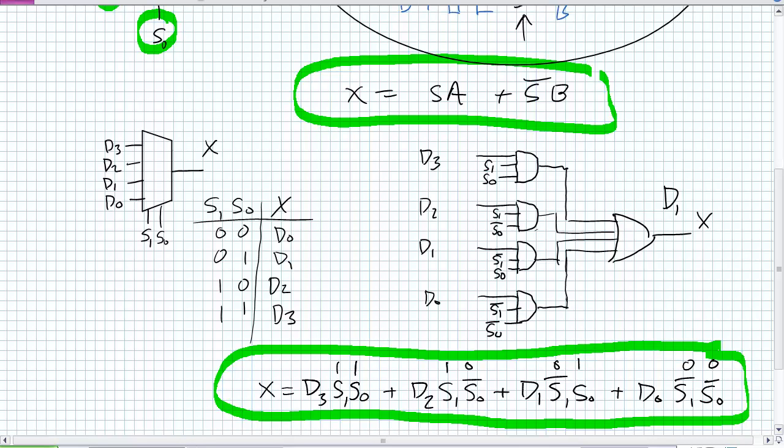Go to an 8-to-1, go to a 16-to-1, go to a 32-to-1 using a structural approach. Okay, let's go ahead and I'm going to clean this up here and let's go back just to our 2-to-1. And what I'm trying to do is just closely parallel what I've done with parallel binary adders. I'm making a component once and instantiating that several times.